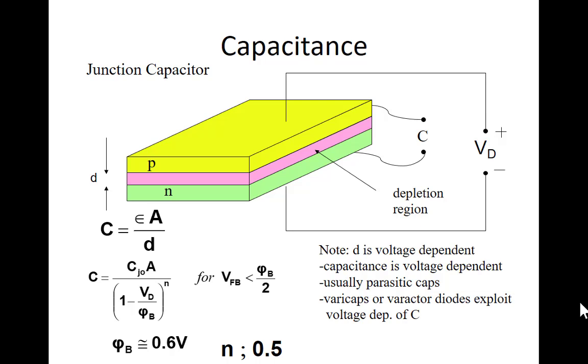We had another name for those. We talked about them in diodes. What do we call it? The diode when we were using it as a capacitor? A varicap. A varicap or a varactor diode, right? But they always exist when you have a PN junction, even if you don't want them. But if you want to make a voltage variable capacitor, you can easily do it.